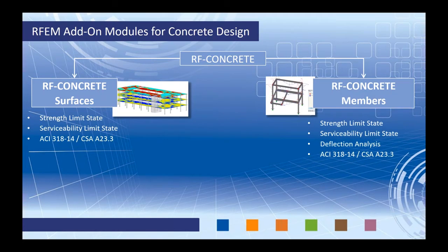The second module is RF-CONCRETE Members. This allows you to run, again, both strength and serviceability limit state design. We can include deflection analysis here for serviceability according to the ACI, CSA, international standards for 1D members, so beams and columns.